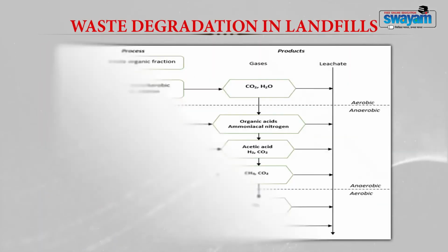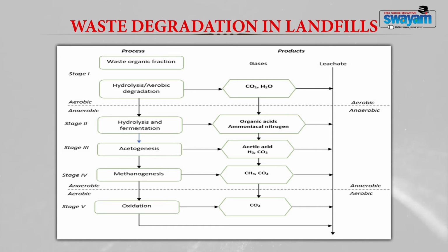Now, let us discuss the waste degradation that occurs within the landfill. You all know that within a landfill, after the waste is loaded, certain physical, chemical and biological reactions take place in the waste matrix. The physical reactions are simple compression, settling, compaction and so on.